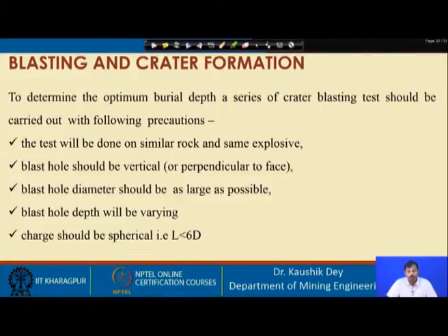Blast holes must be vertical, so that they are perpendicular to the surface. Blast hole diameter should be as large as possible, as is utilizable for our purpose, because there is a constant of the critical diameter also. So, we should overcome that. Not only that, our L by D ratio will give us the optimization of the charge length also, and hole depth we should vary, and the charge must be a spherical one.